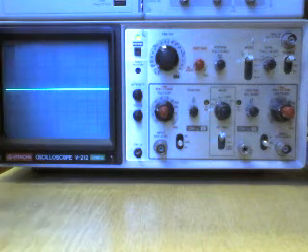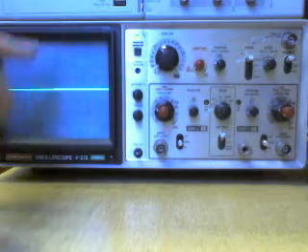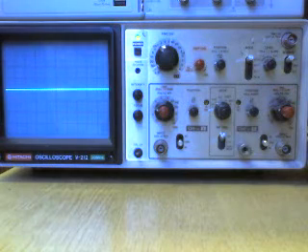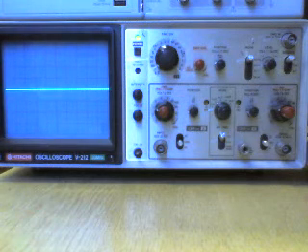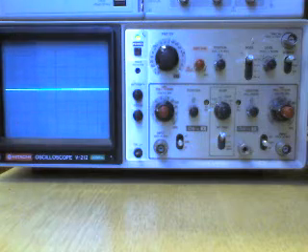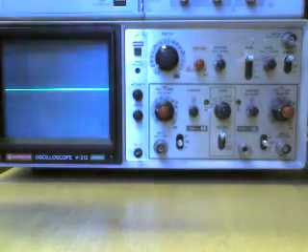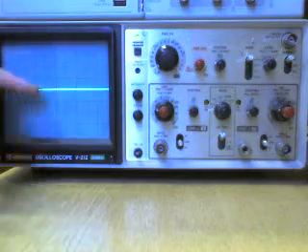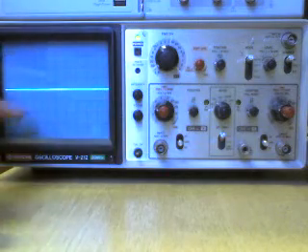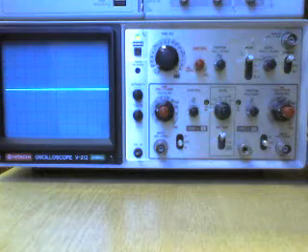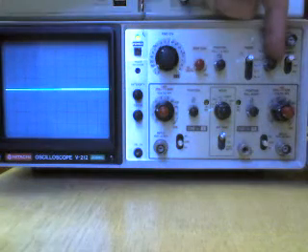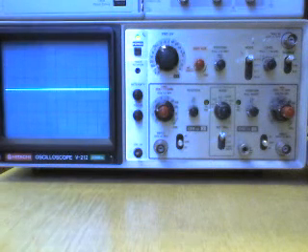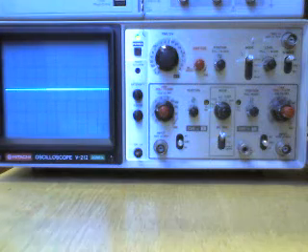So, a sine wave, if we had a sine wave on here, would be continuously scrolling across the screen because it's continuously changing in time, okay. At no point in time is the voltage ever consistent. It's continuously moving up and down, up and down, up and down. That sine wave is, okay. And the only way to really see a stable waveform on the screen, to stop it from scrolling across the screen, moving in time, is to trigger. Okay, and trigger actually tells it the start point of the waveform. Now they're the basic controls.